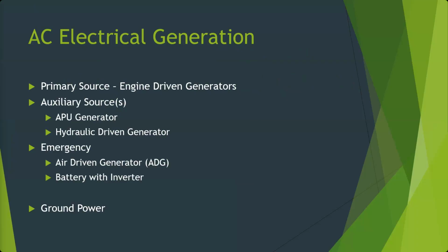Why is this? We use it a lot more often, but you can't use it in the air. So you want the plane to prioritize emergency power. We don't want it looking for ground power when it's a glider in the air. Just hook up a GPU. And yeah, we can't hook up a GPU in flight, and so we don't want it looking for ground power if we're in the air.